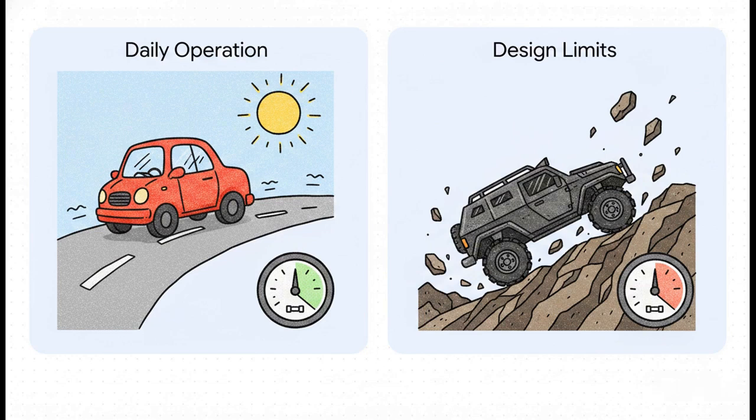Operating pressure is like your normal driving speed. It's the steady state, what the system runs at day to day. It's the standard value you see on the DCS control screen on a normal Tuesday afternoon. Contrast that with design pressure, which is your maximum car capability. If you normally drive at 80 kilometers per hour, you don't buy a car that maxes out and rattles apart at 81 kilometers per hour. You buy one rated for much higher speeds because traffic fluctuations, downhill slopes, and sudden emergencies happen. Your piping is exactly the same. It experiences thermal expansion, surge pressures, and process upsets.